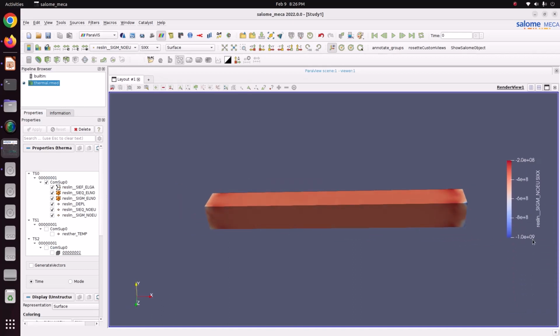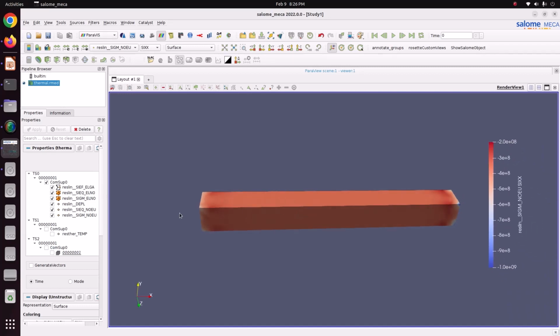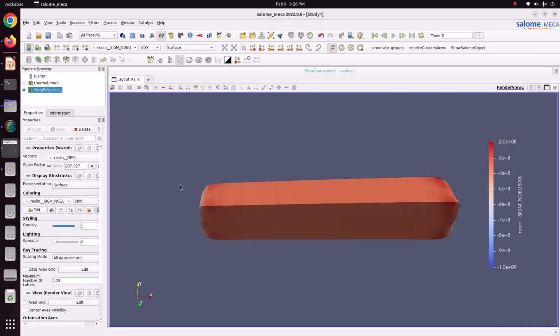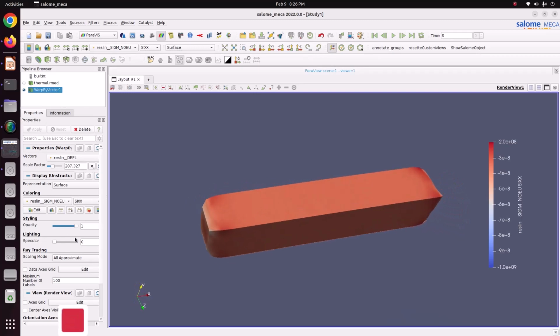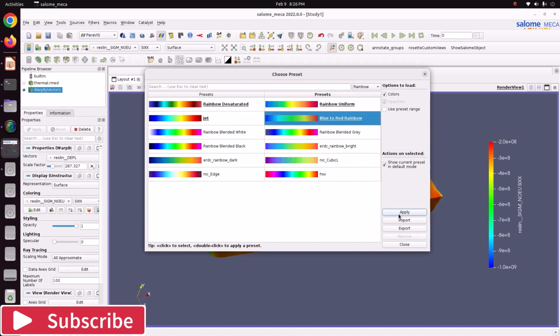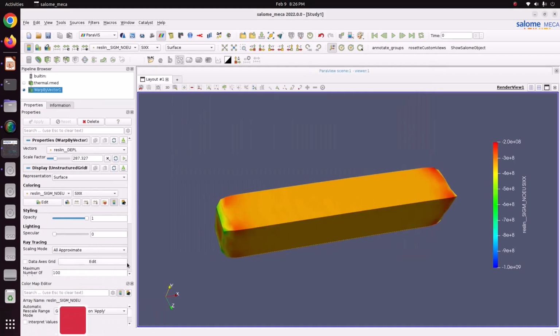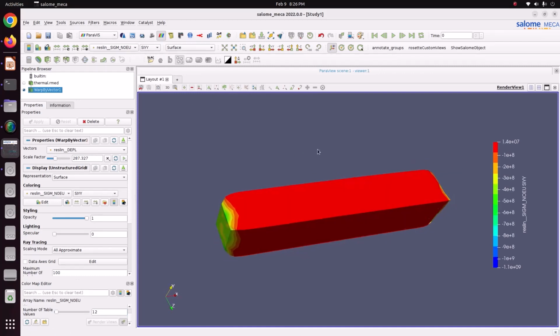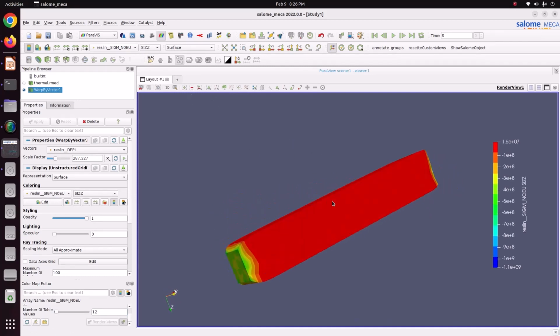Here you can see we are getting the compressive stress. That is because we are arresting the expansions. If you want to see the deformed shape, you just apply here. Give some scale value, just apply it. So this is the way it is going to behave. So see the stress value in the blue to red rainbow color. We can simply modify it here. So this is the way we can check it. This is the sigma yy value and sigma zz value.